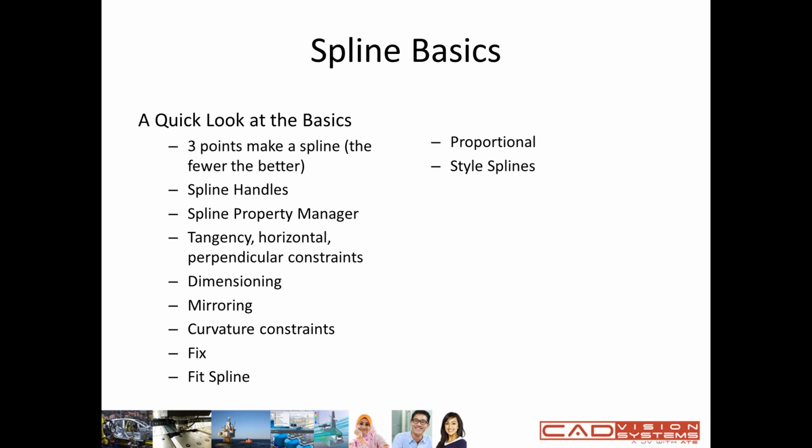Style spline is actually a new feature in SolidWorks 2014. The creation of style spline is slightly different from a normal spline, and we'll see how that benefits us. All in all, for the spline, we'll be taking a look at their curvature combs, so we can see the results as we design our splines. So let's go on to SolidWorks.